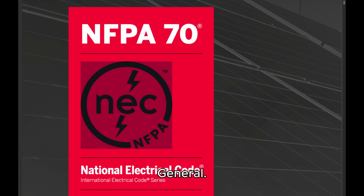Nominal. 110.30 General. Conductors and equipment used on circuits over 1000 volts nominal shall comply with Part I of this article and with 110.30 through 110.41, which supplement or modify Part I. In no case shall the provisions of this part apply to equipment on the supply side of the service point.